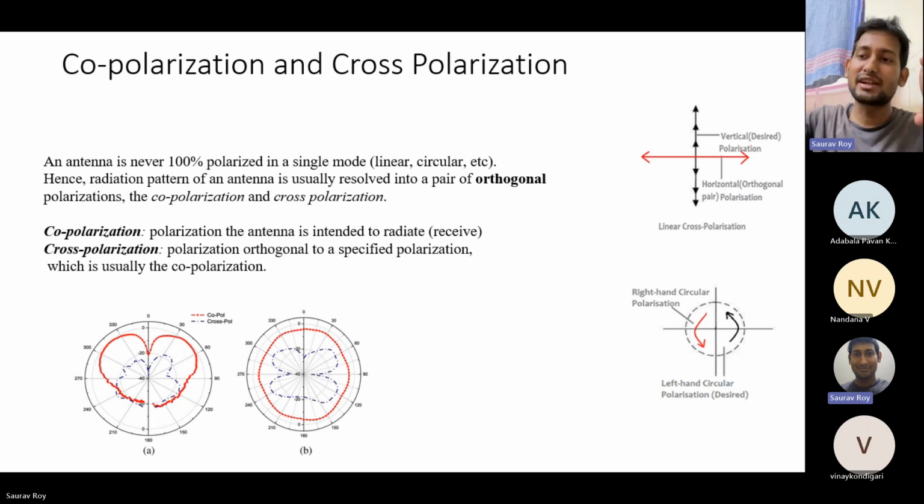When this happens, this pattern, if you measure like this, is called H co-polarization. Now, if you keep your reference antenna the same and move your transmit antenna to the other plane, the E plane, this will be called H cross polarization. This will be H co and this will be H cross. So now you see all is in reference to your reference antenna. Your reference antenna has to be placed in some plane. From that you now understand what is happening. So in total we generally take 4 measurements: E co, E cross, H co, H cross.